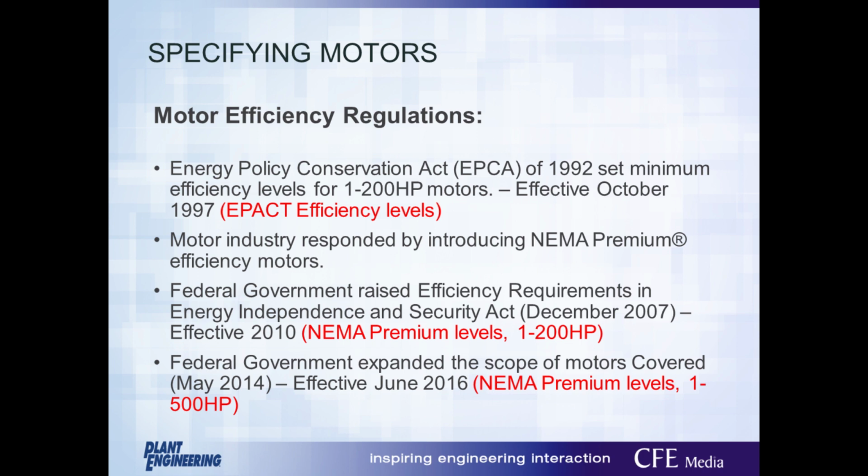The efficiency number listed on a motor nameplate isn't necessarily what it actually operates at. It could be higher, it could be lower. From my experience, most of the time it's going to be lower. It's always good to perform quality checks on your motor suppliers to ensure motor build quality and running efficiency aren't degrading over time.